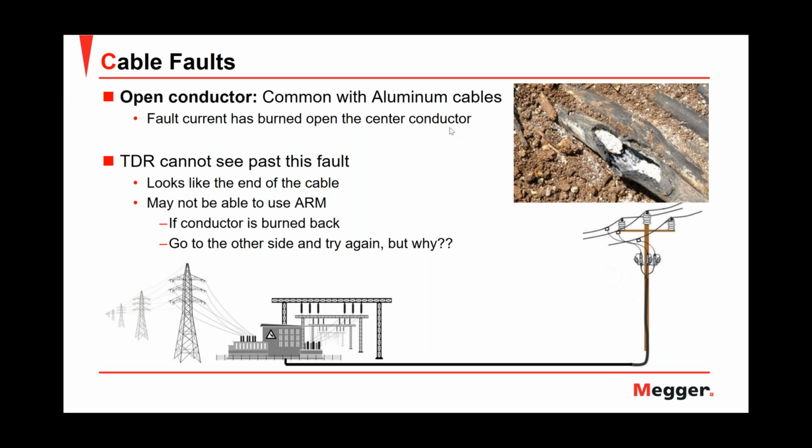In this kind of fault, the TDR cannot see past it, and it looks like it's the end of the cable because we have an open conductor.